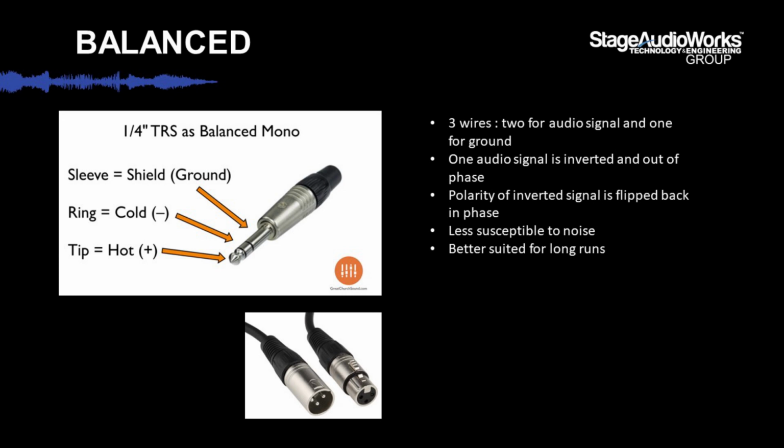That's basically a very common type of issue where people have taken a stereo unbalanced signal, so 2 unbalanced signals, and plugged it into a single balanced mono input. Obviously, if you think about what Ross described about phase, you're putting the left channel to the in-phase input, the right channel to the out-of-phase input, and then those are being inverted. So what you're hearing is the result of the left and right signals being cancelled out.